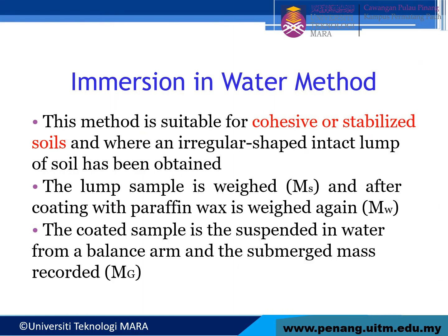Okay, immersion in water method. This method is suitable for cohesive or stabilized soil, where an irregularly shaped lump of soil has been obtained. The lump sample is weighed, and after coating with paraffin wax, it is weighed again. The coated sample is suspended in water from the balance arm, and the submerged mass is recorded.